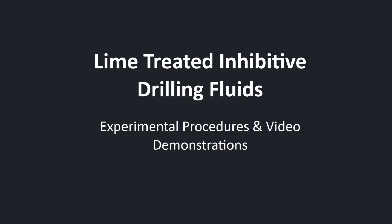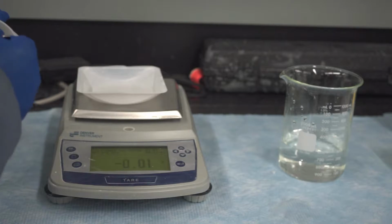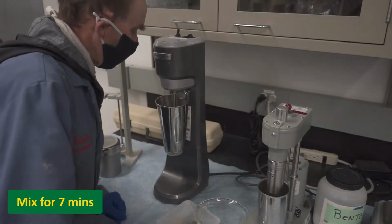In this third video, the experimental procedure will be described and video demonstrations of the lab will be shown. First, a mud sample must be prepared with the mud mixer. Mix 25 grams of bentonite with 350 cc's of water for 7 minutes.